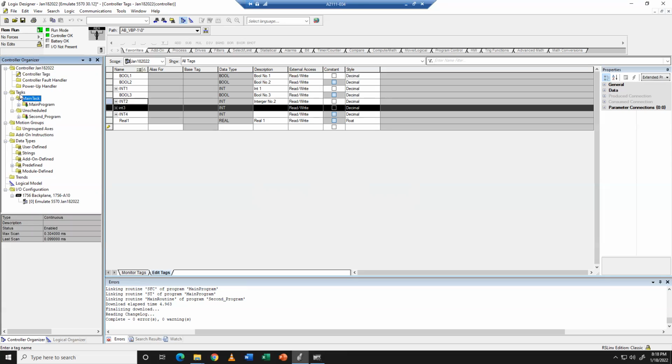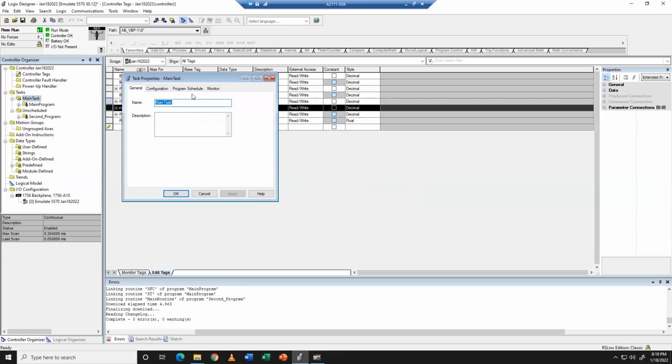got going on. So I was talking about main task. We can see here as this one, I said it runs kind of continuously. It will go through and run the program in order, the scheduled programs. Main program will complete, and we'll come back to the top. You got some statistics in here, how long it takes to run through the entire program, milliseconds. Looks like something took 92 milliseconds at some point.